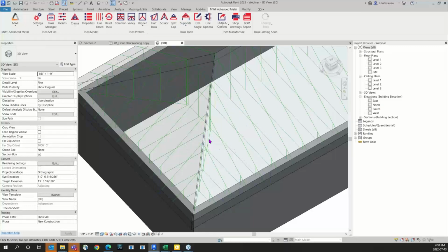We have 3 main ways of creating these envelopes: truss profile commands, line-based, and also by drawing lines in Revit and grouping them together. With these first 2 options, we are actually tagging those members on the backend. So we won't have any issues adding auto truss connections.